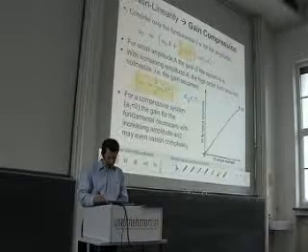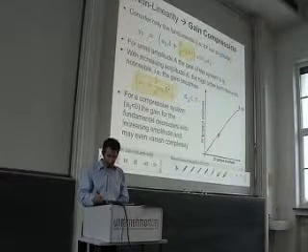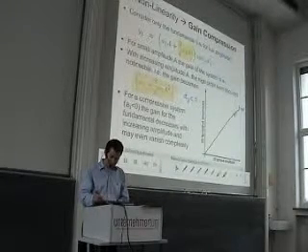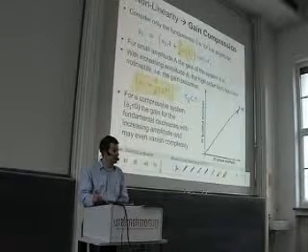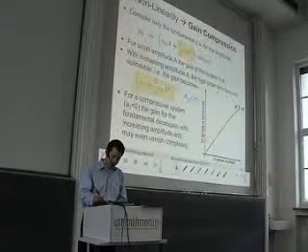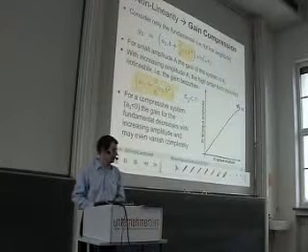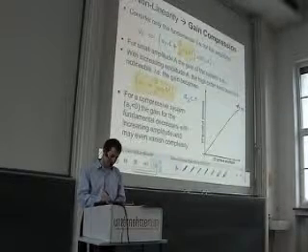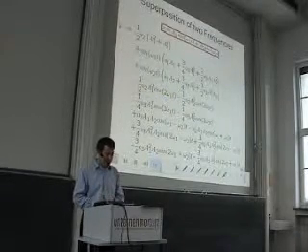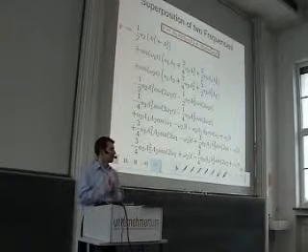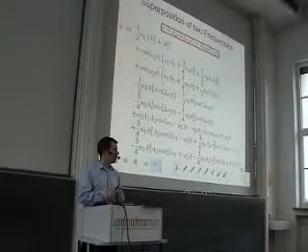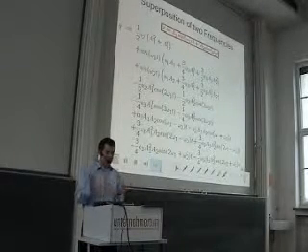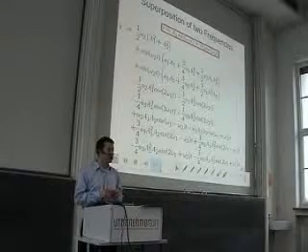Here the gain is this A1, but then if I increase the amplitude even more, then this A3 component comes into play, decreases the gain, and the measure for this effect is the minus 1 dB compression point. What happens if I have two tones, two frequencies, not only a sine omega t, but now we take an A1 sine omega 1 t and an A2 sine omega 2 t.